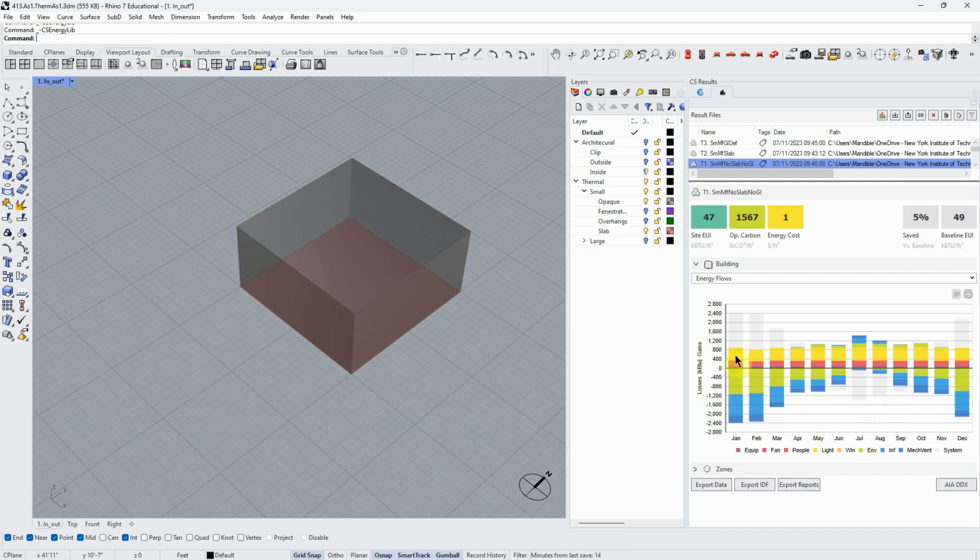Like, well, what do we want? Low-hanging fruit here would probably be to see if we can get our lighting better. Maybe we want to try to improve the air tightness, or just check the setting. But then we're also thinking that air tightness is actually construction. So if we've already built the building, that's going to be difficult, or it's going to cost a lot of money to change. Whereas lighting is something that we can change more easily. But if we haven't built it yet, air tightness is something we can pretty easily fix or improve in many situations, and so we might want to focus on that. So that's what we're looking at here, and the information we're getting to help us in our design. And again, this is just a box, right? So we can do this very early in the process.